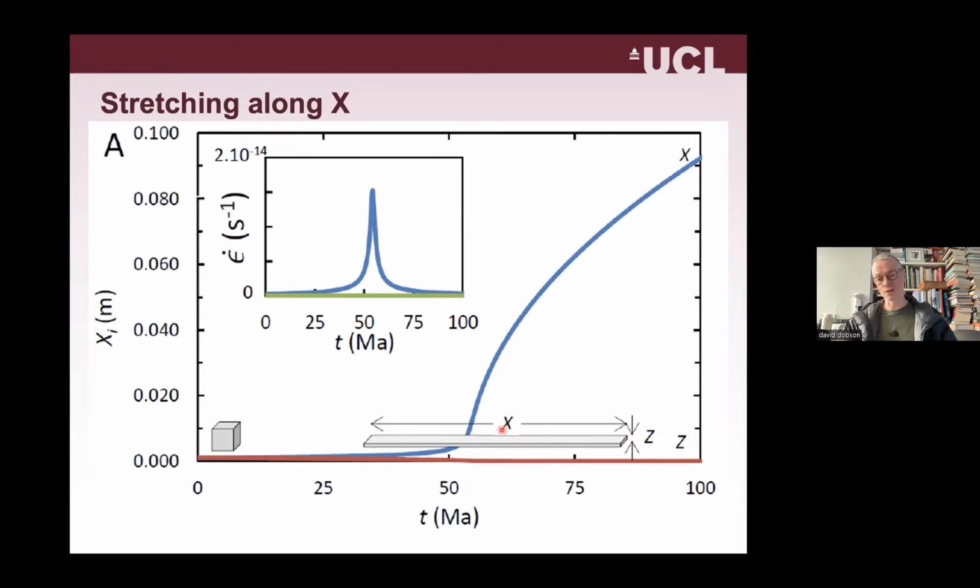And that will happen once the length ratio of X over Z is greater than the square root of the diffusivity in the X direction divided by the diffusivity in the Z direction, okay? So there was 4 orders of magnitude of anisotropy in diffusivity. So once X becomes 100 times longer than Z, then you'll start to get strengthening again, okay? So that's fine. But is it reasonable for crystals to end up being 100 times longer in their thin direction? And remember, there's not been much deformation in the B direction, in the Y direction, in the slowest diffusion direction. So you end up with crystals at this point where it's straining at its very fastest with an aspect ratio of 100 to 10 to 1, approximately, okay?